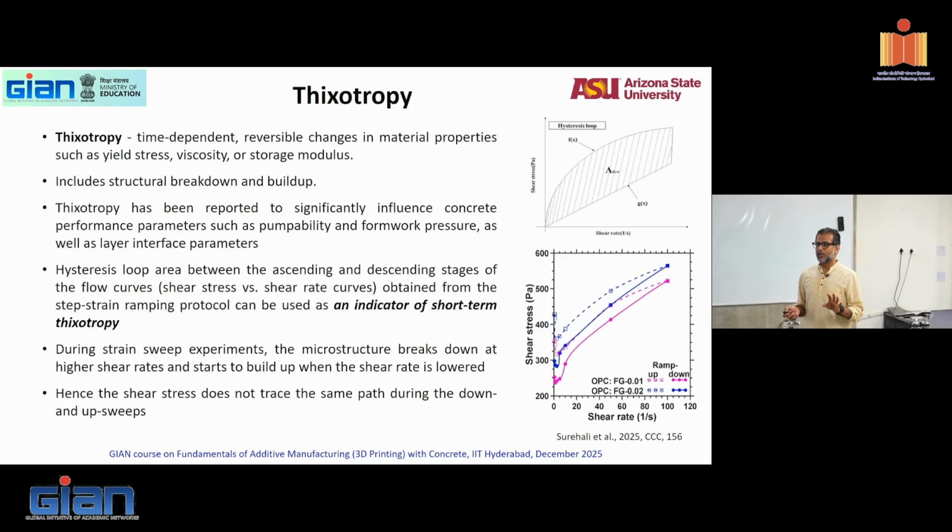Now, thixotropy. So now we get to the idea of thixotropy. Again, you heard this yesterday. This is the time-dependent reversible changes. It could be change in yield stress, it could be change in viscosity, it could be change in storage modulus. Any time-dependent change in a rheological property that is reversible is called thixotropy. Includes structural breakdown and buildup.